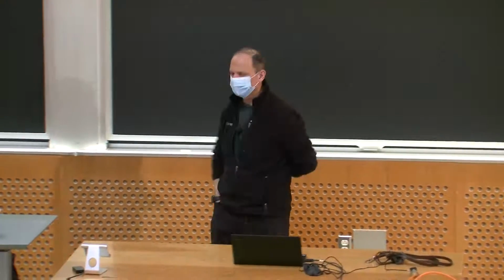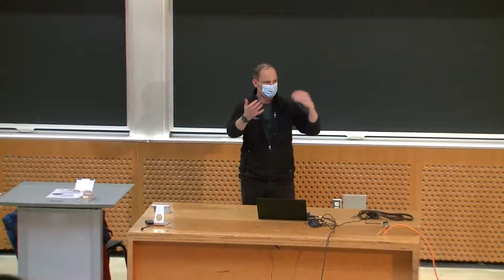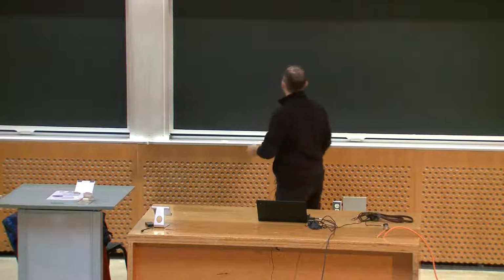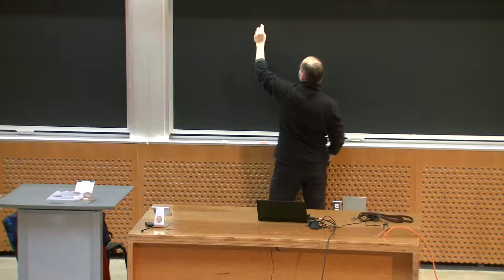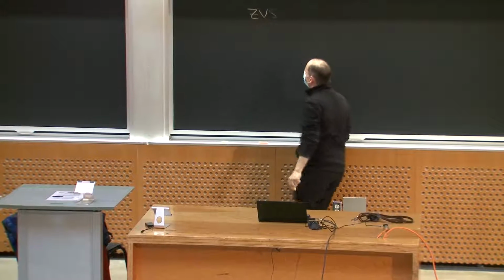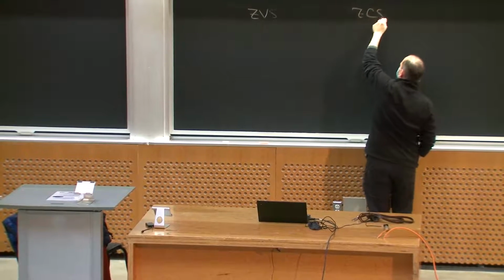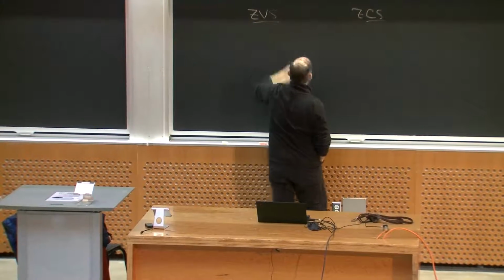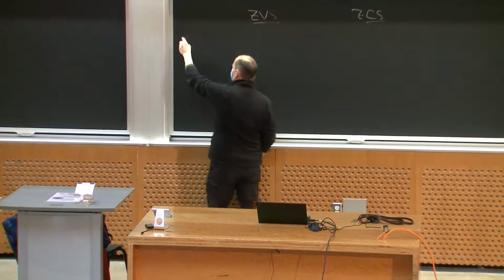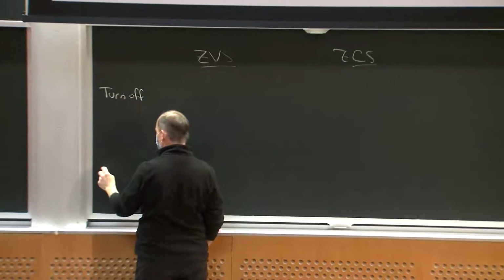I'd like to continue our discussion of soft-switched power converters today. If you'll recall, when we think of soft switching, we're thinking of the switching transitions when we're commutating between devices. I can consider zero voltage switching, ZVS, and zero current switching, ZCS. In some switching transitions, you can get a combination of both, depending upon the design. But we also have to think about switch turn off and switch turn on.